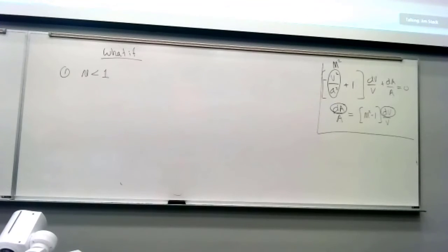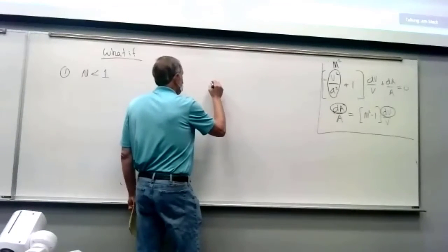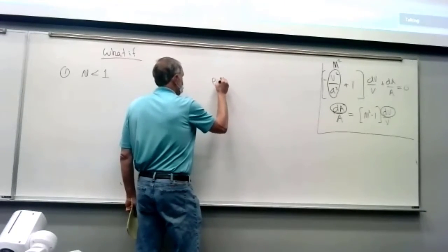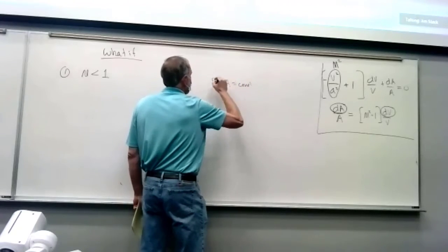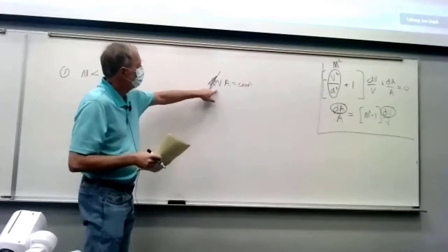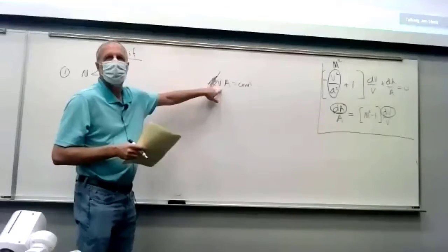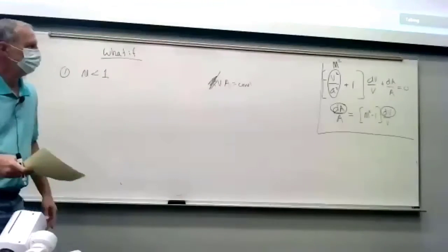We have conservation of mass where you can cancel out the densities. For really low speed flow, we know that rho VA is constant, and the density can cancel out. So here we get a real direct relationship between area and velocity. And we know if we increase the area, the velocity goes down and vice versa.